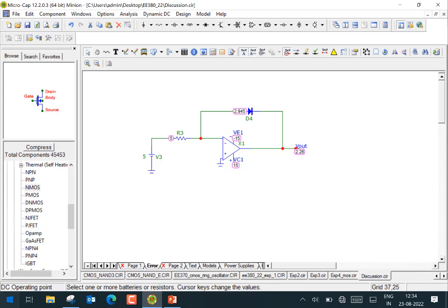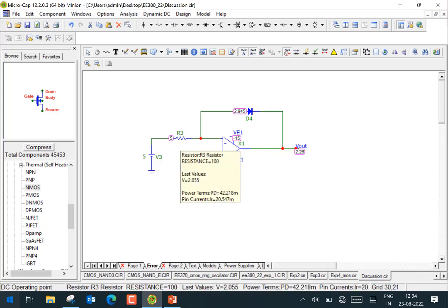It varies from op-amp to op-amp here. So this can handle a maximum current of, let's say, 25 milliamperes. And then the thing was, after looking at it, is that current limit getting violated? So we checked what is the value of the resistor here.